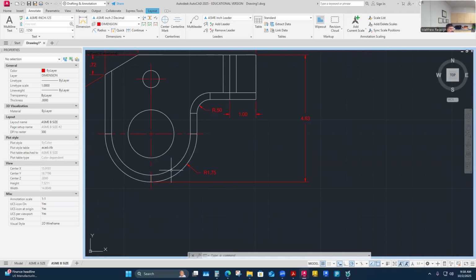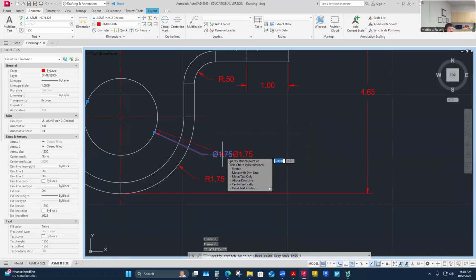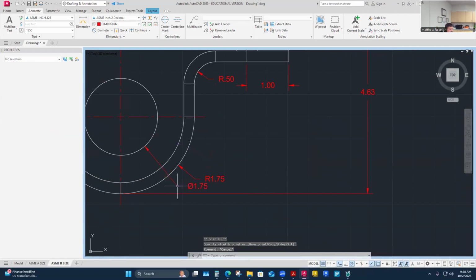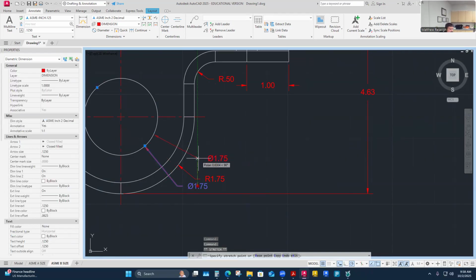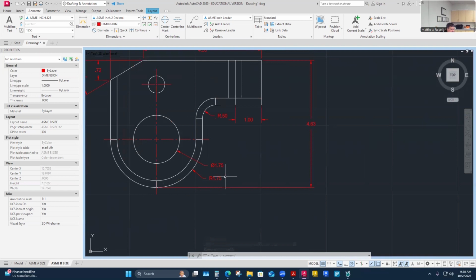And I'll move to that inner circle now, which I've determined has got to have its size. So this is a great place to catch its size. There's only one of those. And I might move these. The rules on leader lines are they like to be at 45-degree angles. But of course, I may have to move those in relation to other things that are going on, so I'm probably breaking the rule a little bit. It's like a 30-degree angle, but I haven't totally decided that's where it lives anyway. I just know that I've captured the size.